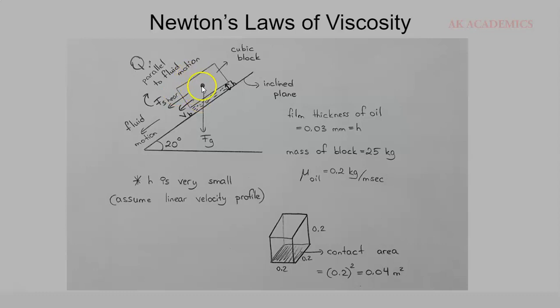Between the cubic block and this inclined plane, we have a liquid, and that liquid is oil. We have oil right in between here. Now, this cubic block is going to slide down, and as it slides down, it simply means that the shear force is going to be towards the direction that the cubic block slides. Again, direction of motion, like I mentioned, is downward. So the shear force will be downward, and the shear force is parallel to the fluid motion.